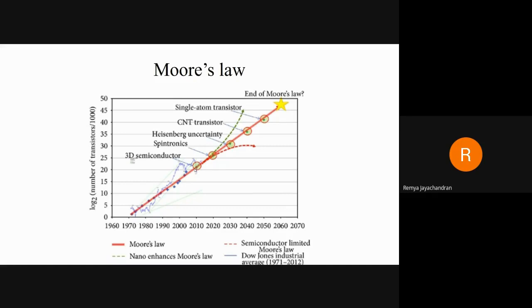And you can see that as we scale down the transistor, reducing its dimension, the distance between the source and the drain is reducing. So that will create an interaction between the source and the drain regions. So the second order effects will be dominant for small devices.